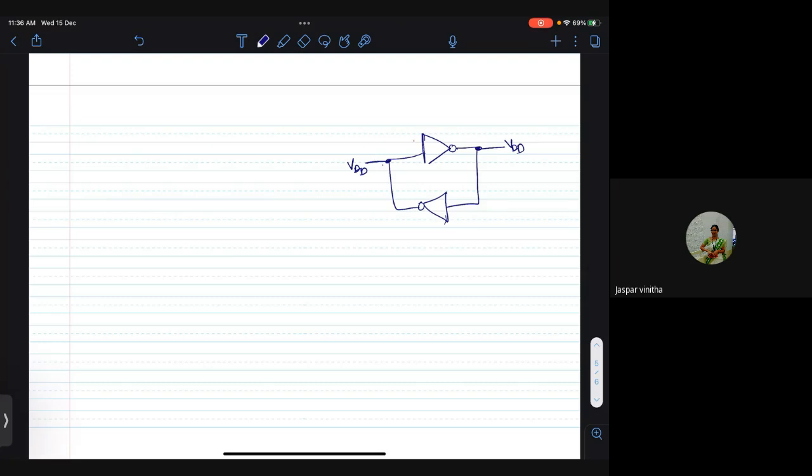Okay, so if I pre-charge both the nodes to VDD, if I look at the butterfly diagram, I'm actually in an undefined state, or what you say, unstable state, right? This circuit has only two stable states. One is at this point and the other one is at this point. This is the metastable state. As I said, we will not discuss too much about metastability in this session.